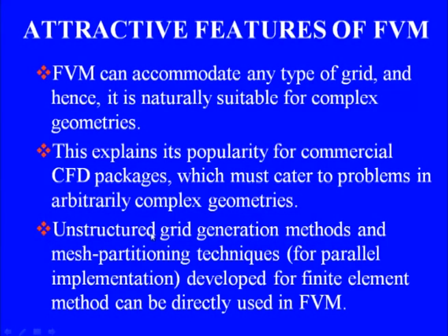So, these two developments, the developments in unstructured grid generation methods and mesh partitioning techniques, which were originally developed for the finite element method, can be directly used in the finite volume method, and they have contributed greatly to the popularity of the finite volume method for solving flow problems in complex geometries. And that is the reason why the industrial strength commercial CFD packages are based on the finite volume method, wherein we can import a mesh which is generated using an unstructured grid generator for finite element analysis and solve our problem.